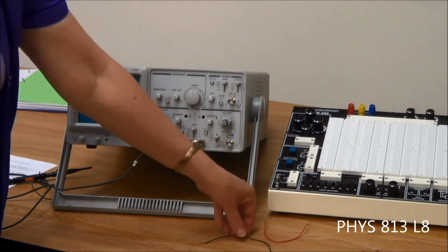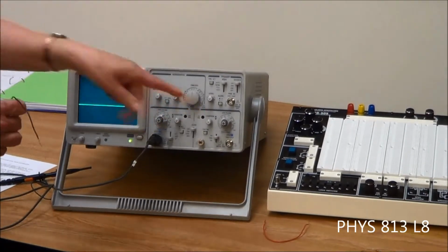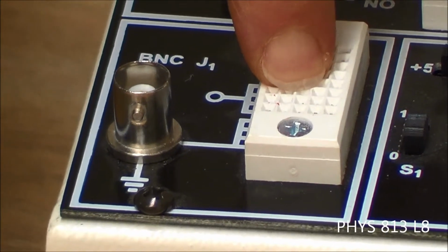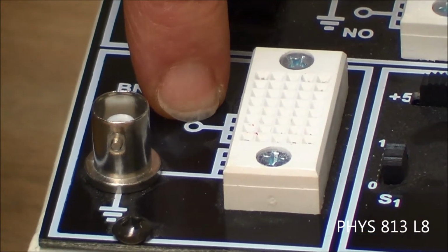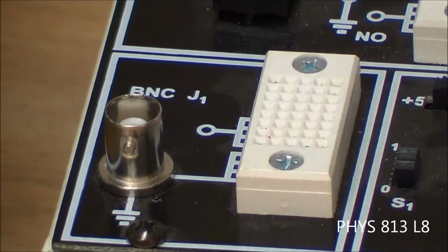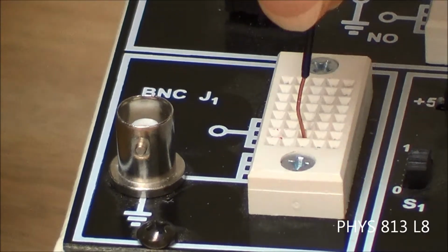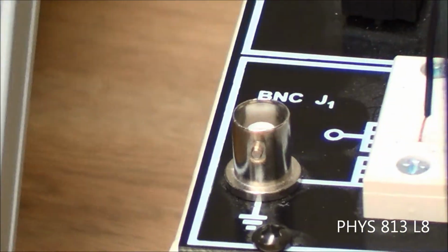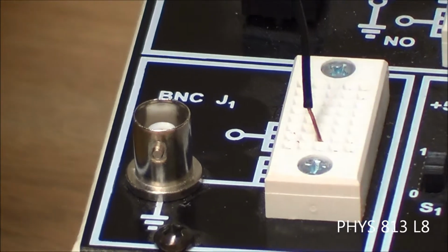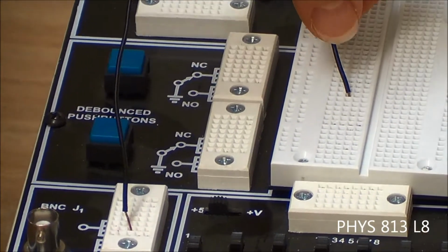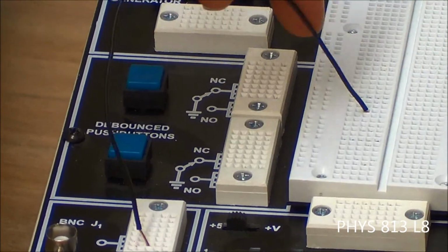Okay, so what we're going to do is we need to go from ground, and if you notice here, there's a white line from the outside over to several of these rows. There's a small circle here, and this goes to the inside. We want to go to the outside, so we're going to just put one of our stripped wires into any of these. Let's see, there's actually 4 rows there. You can put it into any hole in any of those 4 rows. Then we're going to just put it over here on the circuit board any place that we want. We'll have to put it in a particular place a little bit later, but right now we can just put it there.